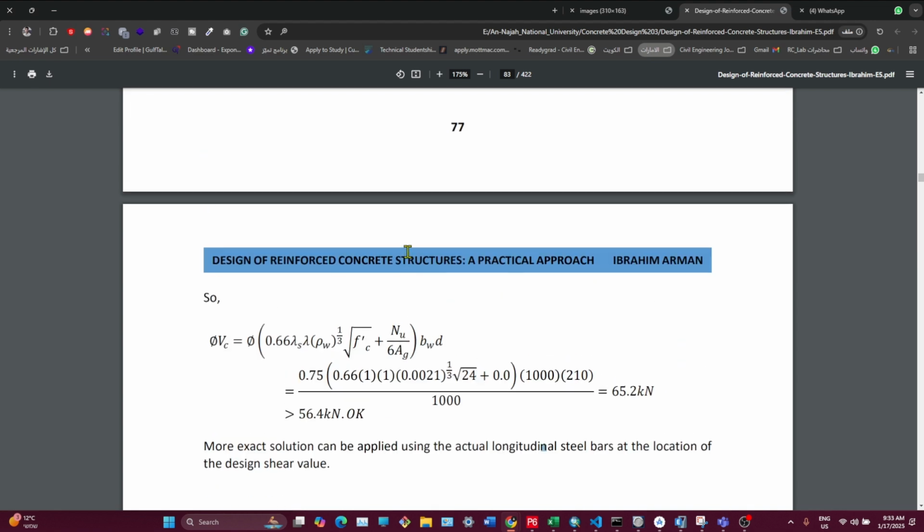So, I mean, the algorithm to solve an example like this is, first of all, to compute the flexural reinforcement by the moments. Okay, just compute the flexural reinforcement of that strip or the slab or the beam or whatever it is. Then substitute the rho W, the exact rho W in the beam. Then maybe it needs shear reinforcement.